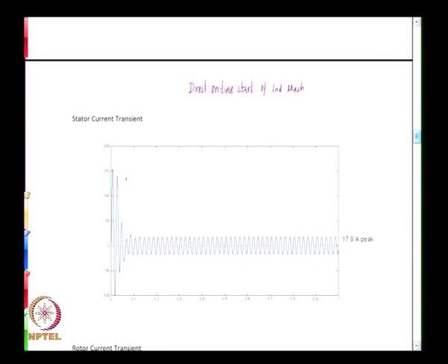So here again there would be a DC inrush initially. You see that this is 150 ampere, whereas here this peak is only 100 ampere, so it indicates it is not really symmetric, and therefore there is likely to be a DC component which starts at some value and then decays down to 0 as it reaches steady state. And this behavior can of course be analyzed by means of the equivalent circuit. Again you must know the speed at which it is going to settle down, and once that is known, one can find the steady state performance using your circuit analysis.